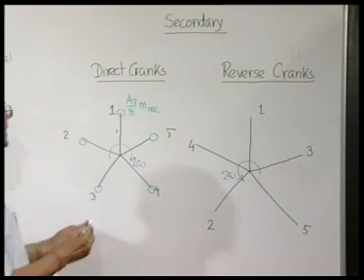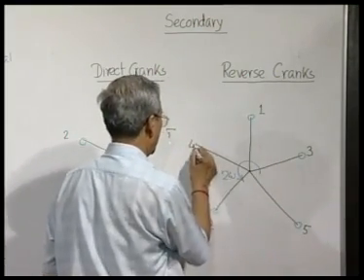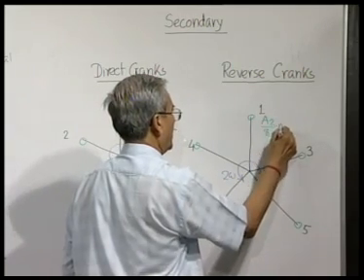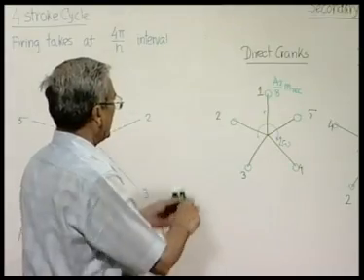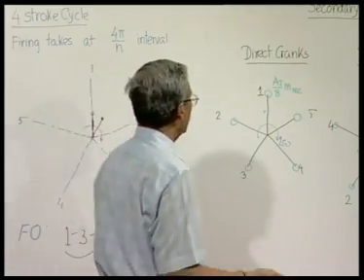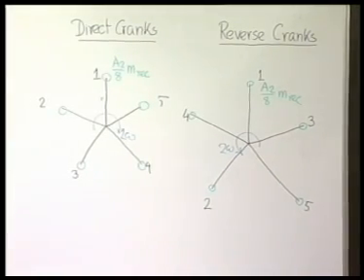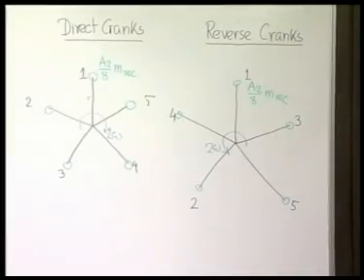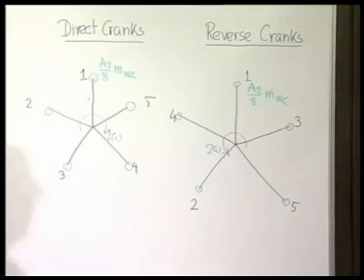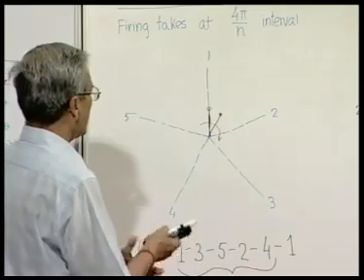If we now place again A2 by 8 m reciprocating at each crank pin, the centrifugal forces produced by the masses attached to the reverse cranks also balance among themselves. So, effectively it means that the secondary is balanced. Following the same procedure, if we now take the fourth order and find the direct and reverse cranks, you can find out whether both indicate a complete balance or not.